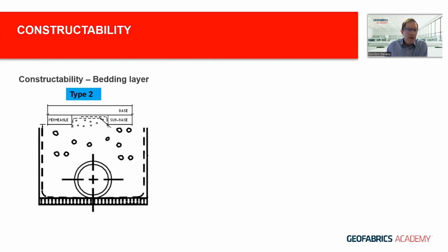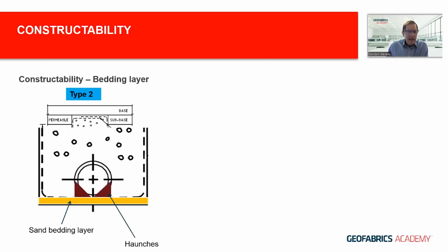And if we zoom in on the round pipe, you'll see that we need a bedding layer to support that particular drain, and you'll need a fill underneath that. So that dictates that there's a minimum criteria for compaction of that fill to support that round pipe to prevent its collapse.